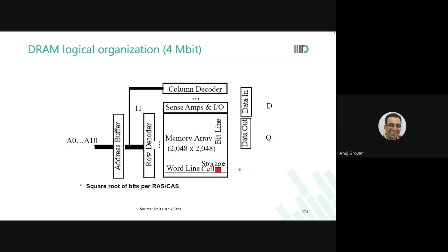As I said, same number of address rows and same number of columns. What you need to do is, when I am using the address bus for row addresses, I will give a row address strobe. So that's one signal. The strobe means one strobe that is coming, okay? And when you are sending a column address, you will send a column address strobe.